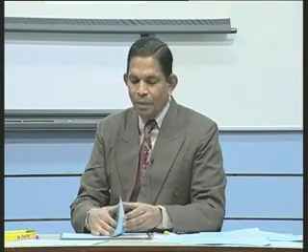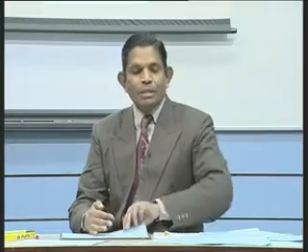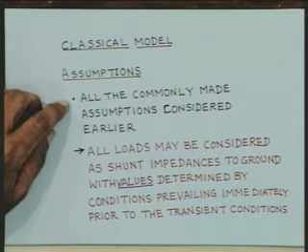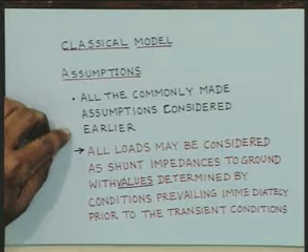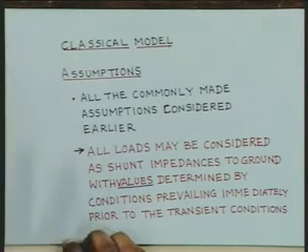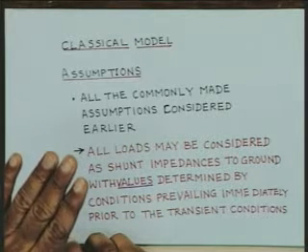Now, our next step will be in solving the multi-machine problem. We have to develop the classical model. When I say we are using the classical approach, we will have to develop the model. Now, in the classical approach for transient stability analysis, we make all those assumptions which were made earlier. These 5 assumptions, I will just reiterate them. First was that mechanical input power remains constant.